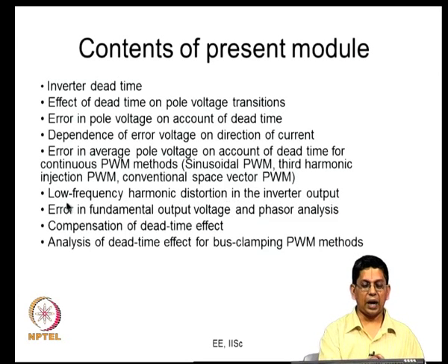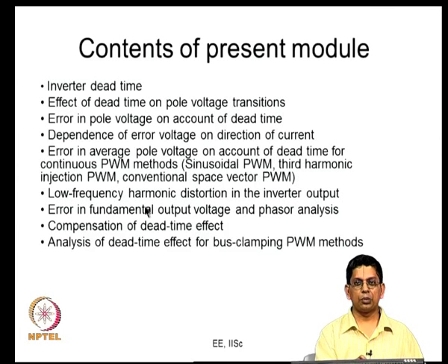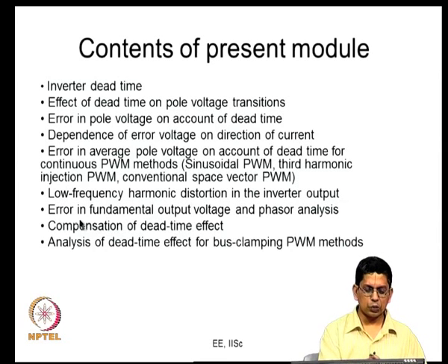So, you will expect high frequency components, but this dead time brings in a certain amount of low frequency components in the inverter output. This is one reason why it is not desired. There is going to be some impact on the quality of the waveform. Then we are also going to look at what could actually be a more important aspect of that.